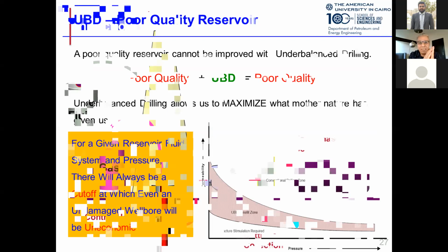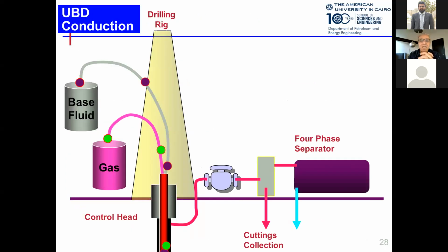So how is the technique conducted? In terms of the drilling, I mentioned earlier that the mud, let's say water-based mud in here, has a density of 1,000 kilograms per cubic meter. Of course, we add some material to the mud, bentonite for example, so the density gets larger. To reduce the density, in order to reduce the value of hydrostatic pressure, we inject gas. We inject, for example, nitrogen, which is quite safe.